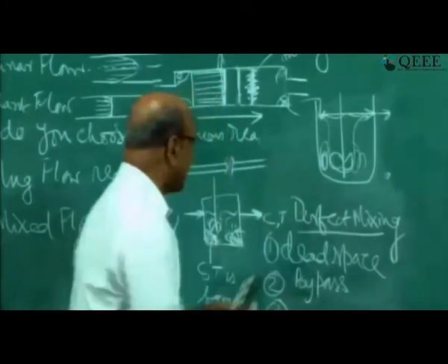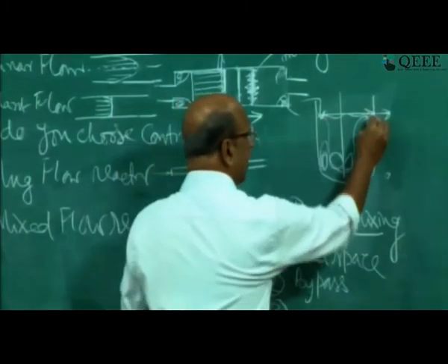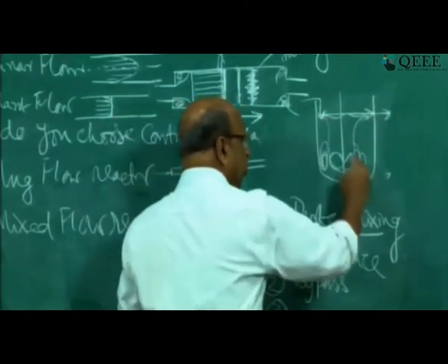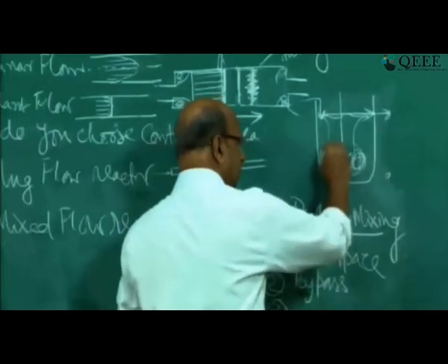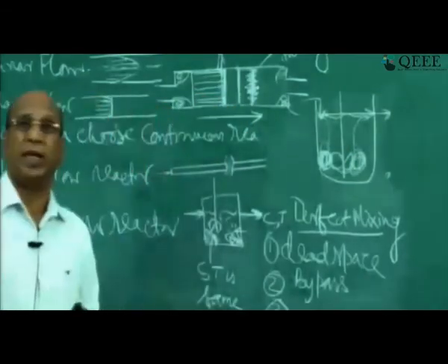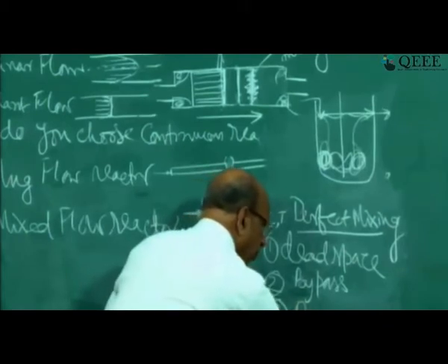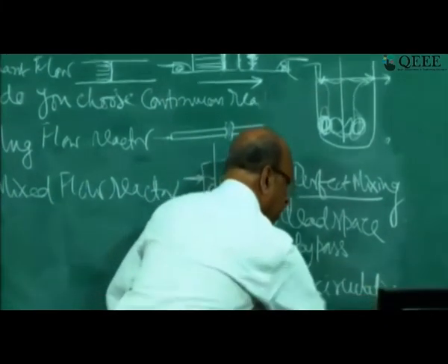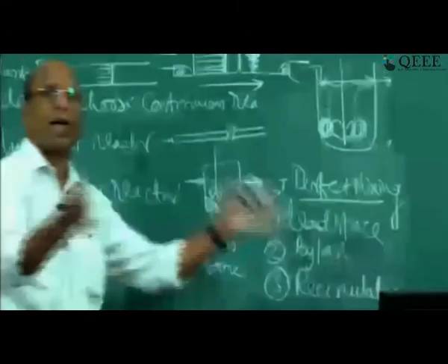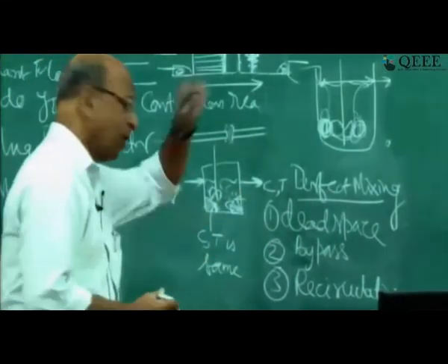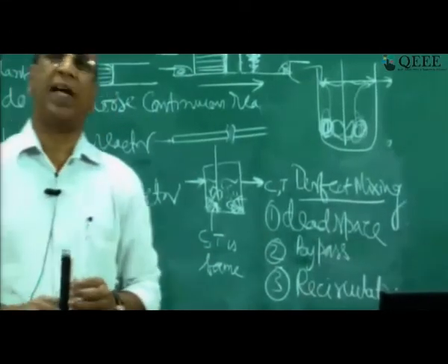It won't mix anywhere else. Near the impellers it will be recirculating. So recirculation zones are also a drawback, a non-ideality in mixed flow reactors.